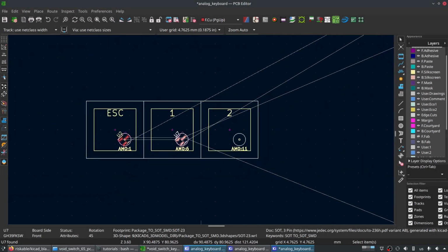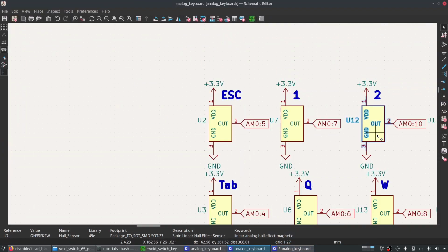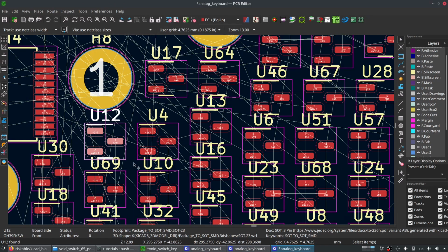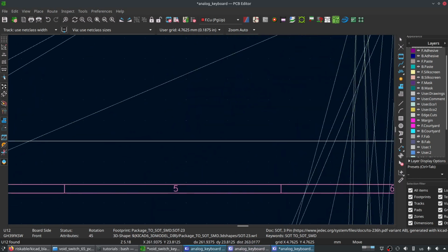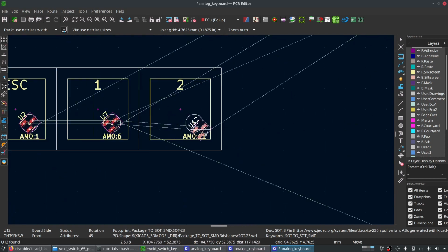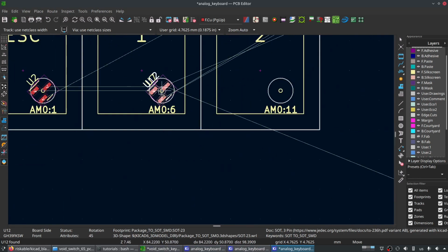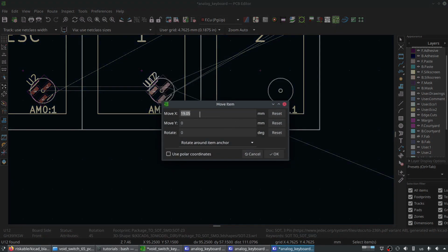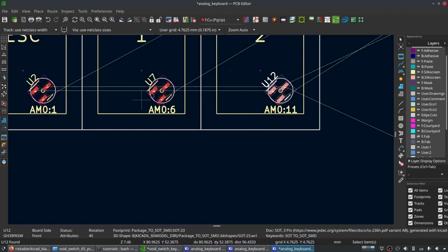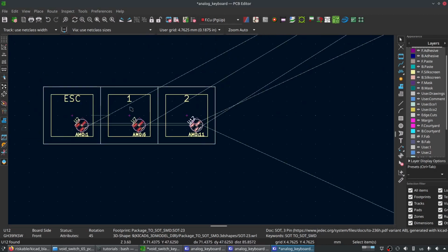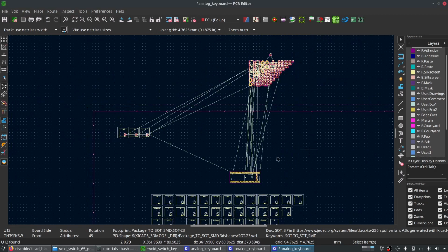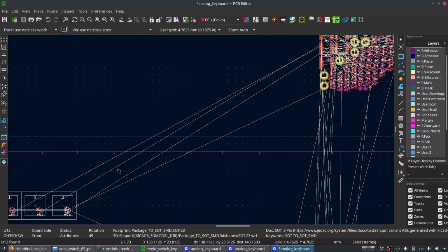Now what's cool about this is if I go to the schematic for 2, let's do this again. Same thing. I'm going to rotate it once. I already hit R to rotate. Let's go over here, and we're going to put it down. Now we hit Shift M, and it remembered the value. So all we have to do is Shift M and then Enter, and we're good. And we can continue this pattern all the way across our keyboard using whatever layout we want.